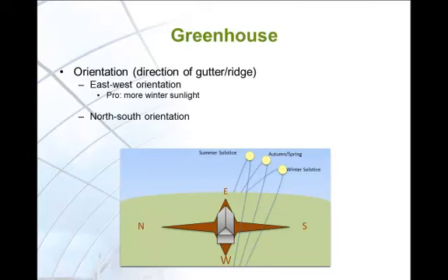The winter sun shines through a sidewall. More plants are located close to a sidewall compared to an end wall, so low winter sun will reach a maximum number of plants. Sidewalls are also typically clear of light obstructions, while the end walls usually have vents, cooling pads, heaters, and doors.